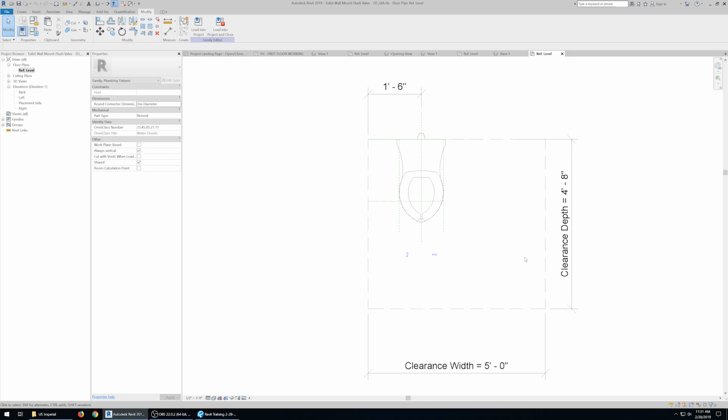Now you have 150 revolves, 150 voids that it's got to compute every single time it wants to regenerate that view. Every time you pan, it's doing the math. Correct. Versus this, which is just some lines that it's got to rotate around, and it's faster, it's smaller, it's a smaller file size when you create it that way as well.